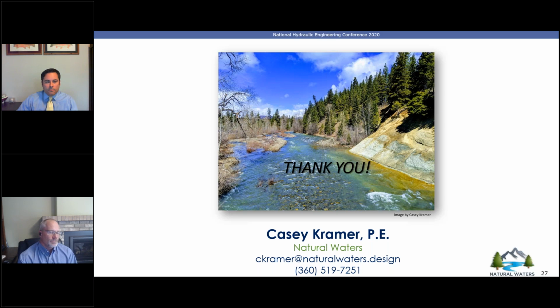I know I've been told several times when the model was very old, or it wasn't available anymore, that we had to go back and recreate it, either in the original format that it was, or if we were going to use a different model, we had to show similar results. That's a challenge. What I've heard in our discussions lately, consistent with what Casey mentioned, is that your requirement will be to not necessarily rerun that model, but match the current effective BFEs within a half a foot. But again, that's based on discussions, and we'll have to see what the final guidance says.